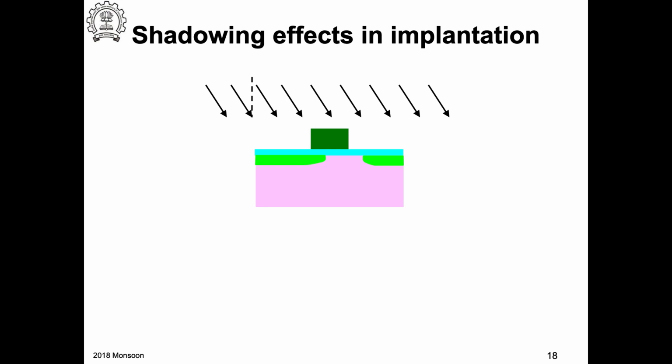So if the reverse bias junction depletion region can go under the gate, I can get electrons. You can see that the PN junction, the moment you get carriers into the depletion region, very high field, there will be sweeping. So a reverse bias PN junction does not conduct because there are not enough minority carriers on the two sides.